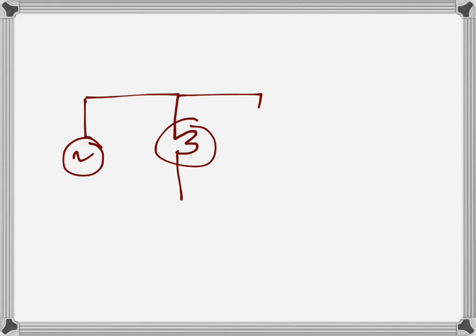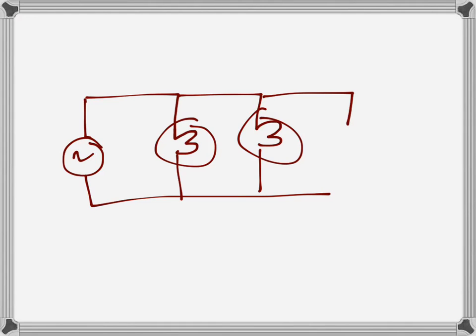If they were connected in parallel, then each of them would get the full 120 volts across, right? So this would get 120 volts, this would get 120 volts, this would get 120 volts, and they would illuminate. Their power absorption would be accordingly 30 watt, 40 watt, 50 watts, and the illumination will be appropriate. So yeah, this problem actually shows why bulb loads are connected in parallel.